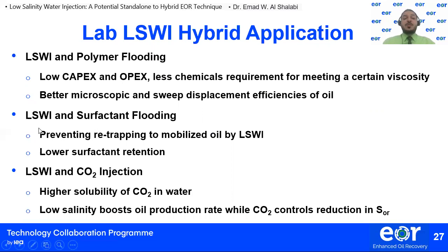Another application is the hybrid of low salinity water injection with surfactant flooding. With low salinity, usually some of those released oil blobs might be retrapped again because capillary pressure is still active. But thanks to the use of surfactant, which kills that capillary pressure, it will help in producing more of the oil. Also, we should not forget the positive effect of low salinity in reducing surfactant retention.